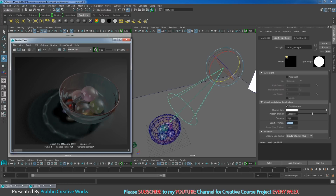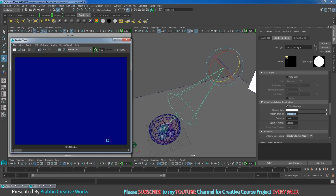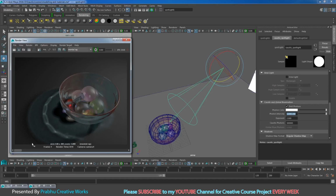Now I will increase my photon intensity much more. I will give 32,000 photon intensity. I will keep this image for comparison and click render again. Now see our caustic pattern intensity has increased. So I will give 50,000 over here. I will keep this image for comparison and click render.